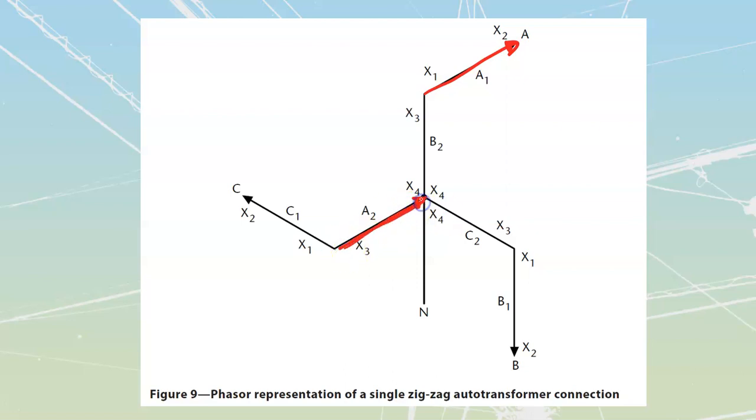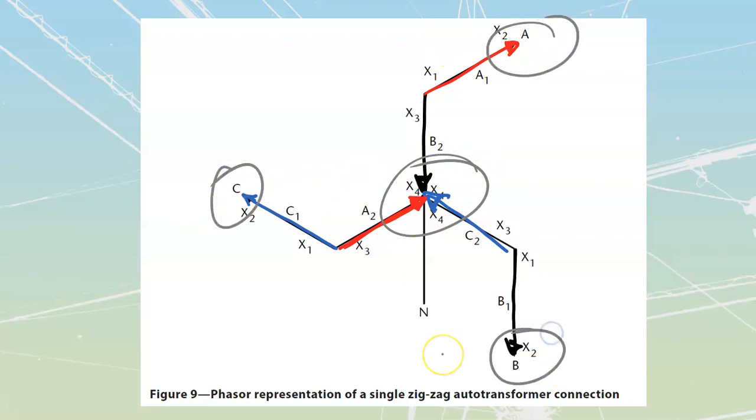So I've got my A winding that is split apart and is going across two of these. My B winding is done the exact same way. Here's an even number on the B, so it's got a head. Here's an even number on the B, so it's going to have an arrowhead. And then my C, done the same way. Even number gets an arrowhead. Even number gets an arrowhead. And what you'll note about this is we get this really cool thing happening, where we have 3 arrowheads pointing in, as well as 3 arrowheads pointing back out of this. Which means that we're going to work out to having some cancellations inside of here. And we're going to talk about that in a second.